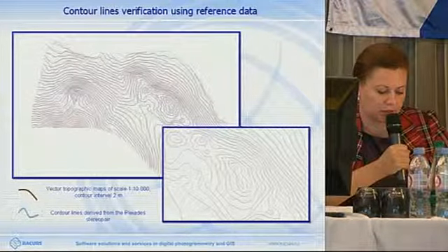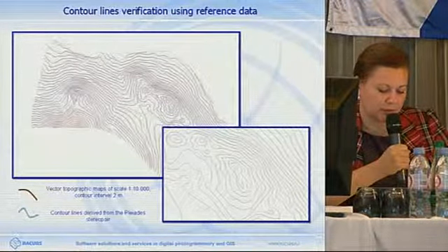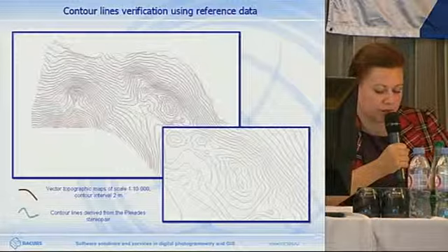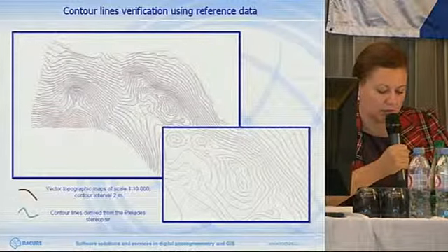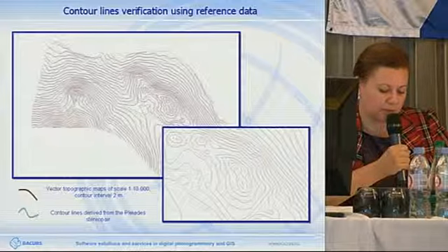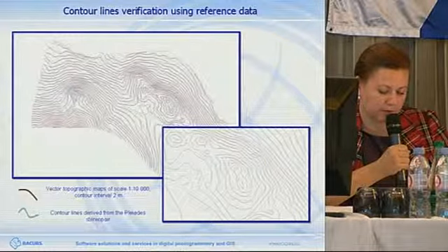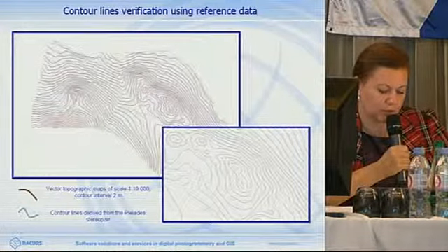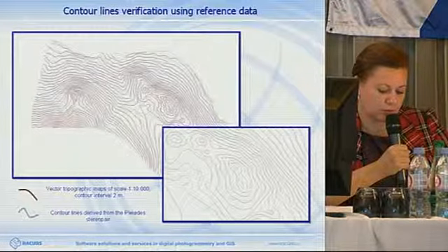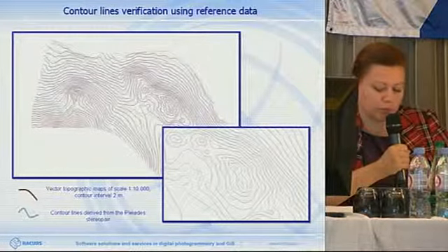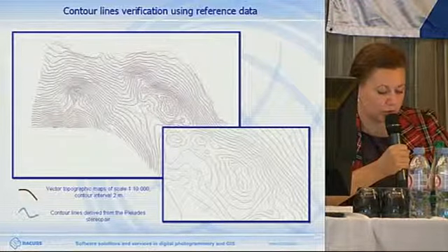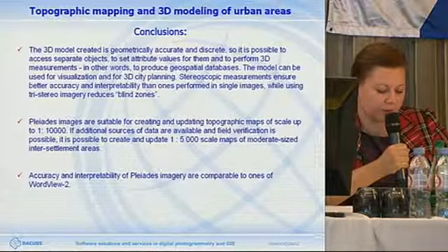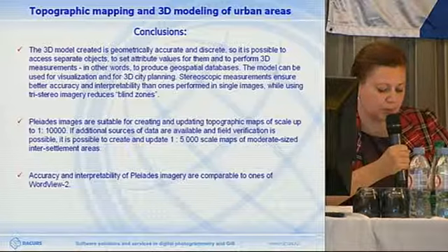I mean digital topographic maps 1 to 10,000 scale with 2 meter spacing shown in brown on the picture, and blue color indicates the resultant picture. The overall form of the relief is shown correctly. The relief, the terrain is somewhat generalized. Hills of 3 to 5 meters are omitted. Perhaps if the angle from which image was made had been changed, we would have had better accuracy.